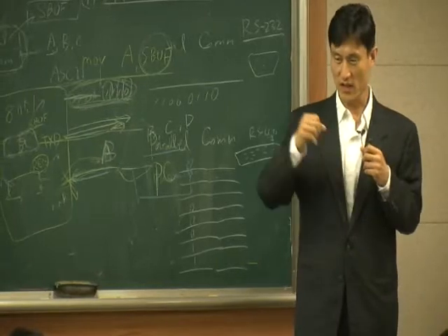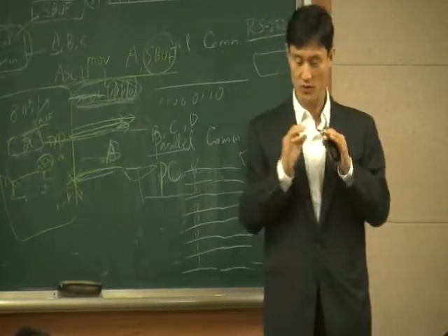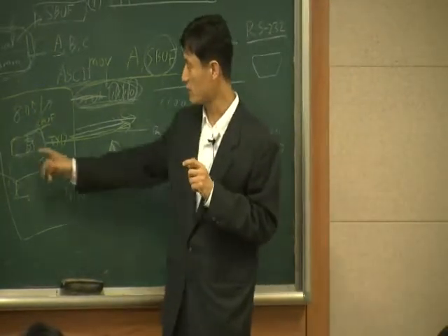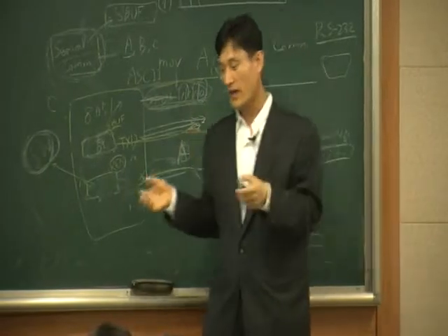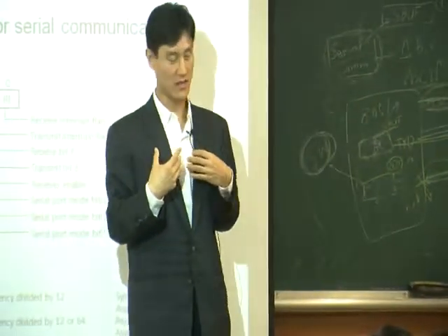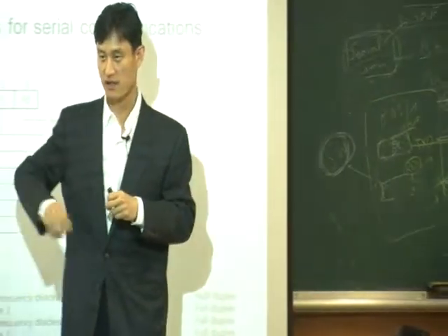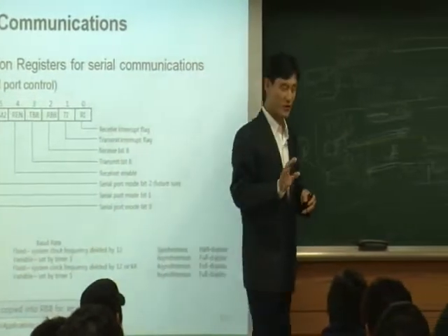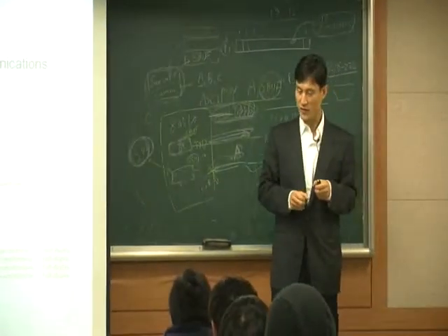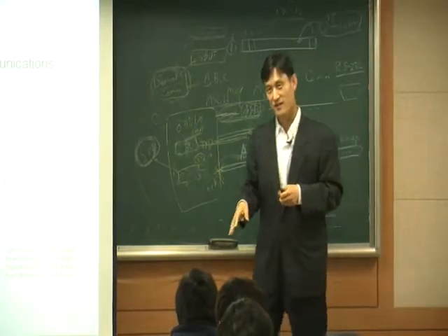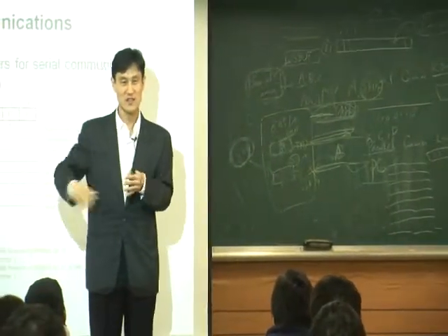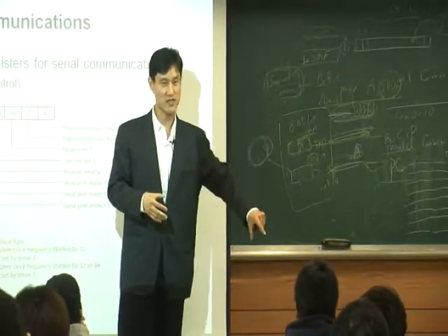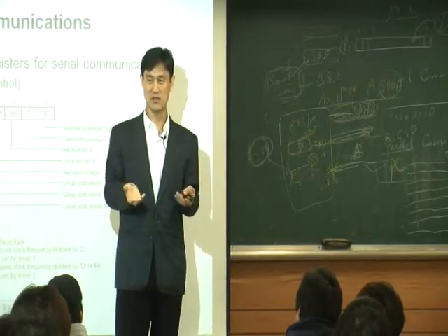Software, what I'm doing is I just write the value into SBUF. That's all I do. And hardware takes the value from SBUF and transmits one by one, 1 bit by 1 bit. But this hardware never talks to the software. So if the software writes the value too fast, then the hardware didn't finish it. I was transmitting A, but in the middle of the transmission, software writes another value. So my transmission is messed up.